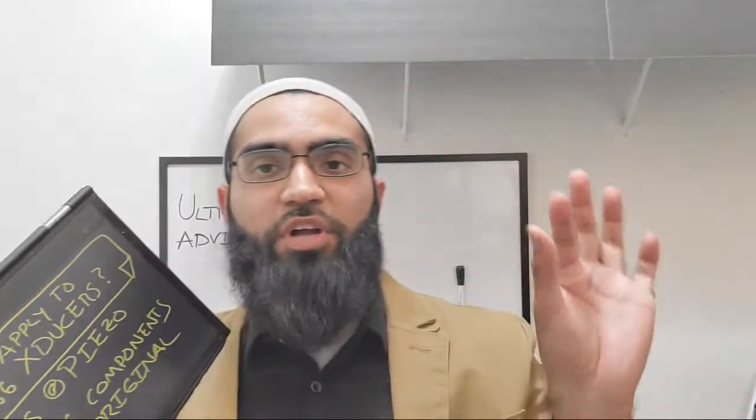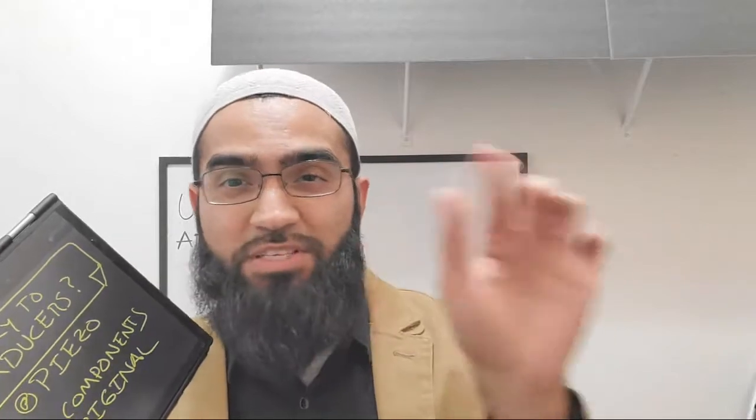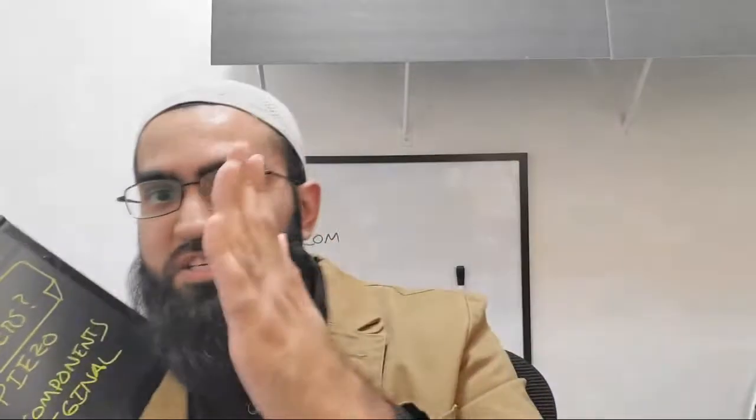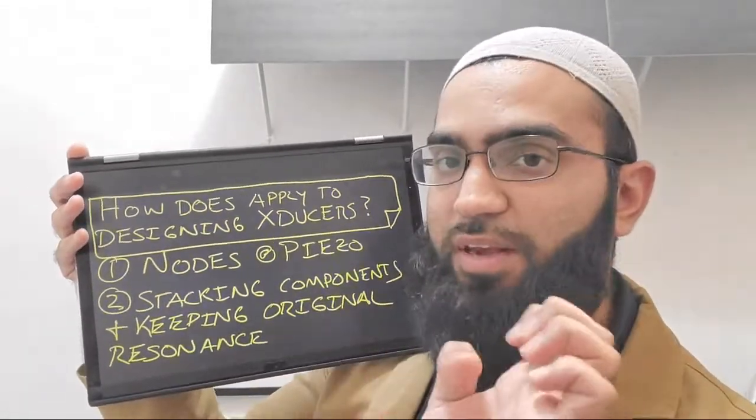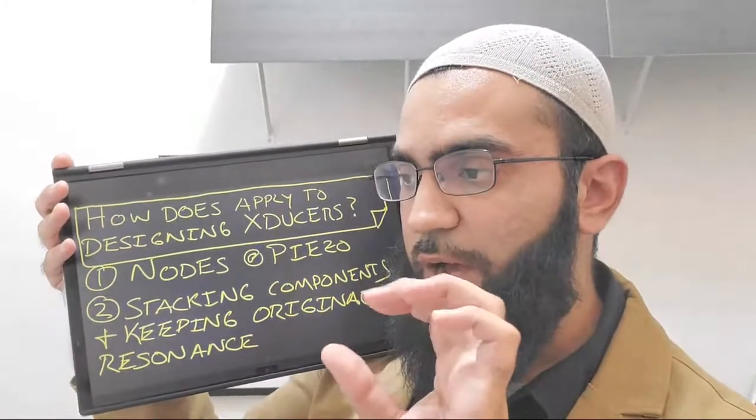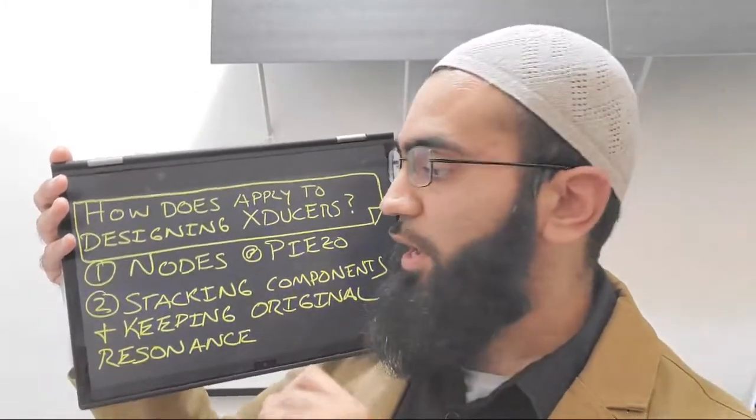So again, when you're attaching the tool, the attachment point is going to be at an antinode, at a point of maximum displacement, in order to minimize stresses at interfaces. Stresses at interfaces are a really bad thing for ultrasonics. It's much better for it to be a high displacement point. That works much better for transferring energy rather than having it be a stress concentration point.